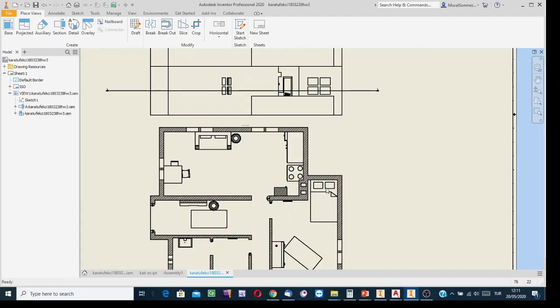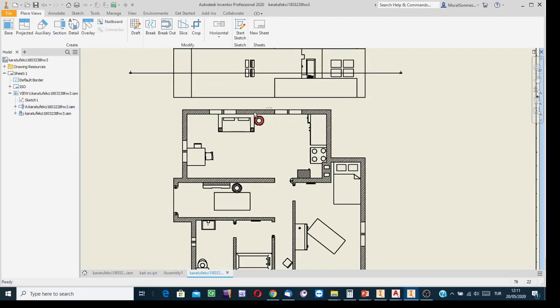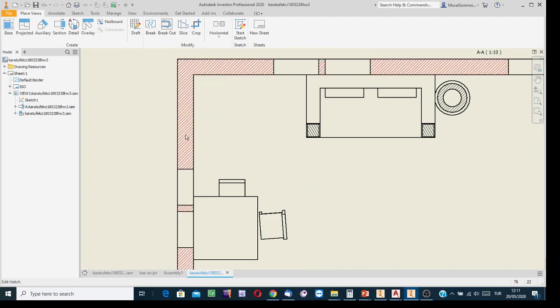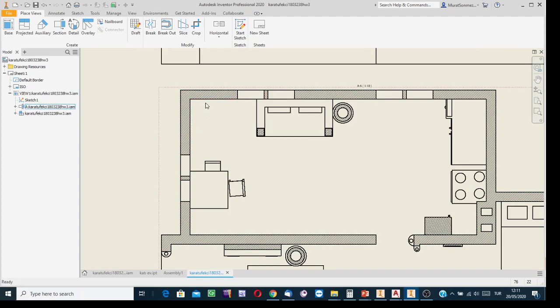Say that the plan view is over there. Well, solid parts are cross-hatched. Inventor knows that it is a sectional view, and on a sectional view, solid parts are to be highlighted. For any kind of material, equally spaced inclined lines can be used.